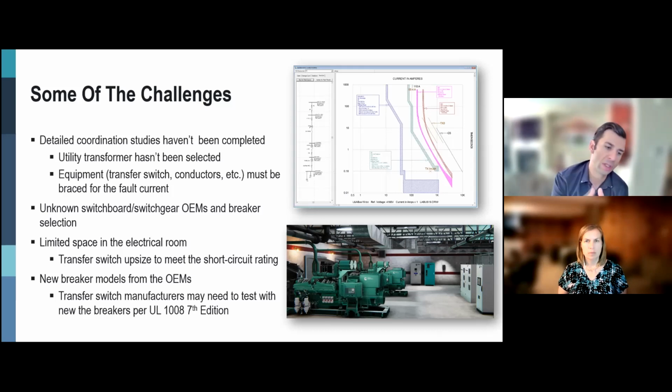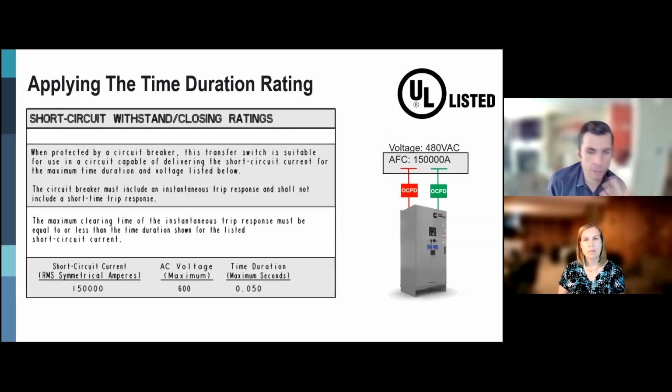Then there are changes to the breakers, new breakers coming from the manufacturers of circuit breakers, and there have been some changes to UL 1008 7th edition. So new testing has to be done for the transfer switch to be tested with a specific breaker. Those are some of the challenges you have as a consultant specifying engineer. What we can do is apply the time duration rating.